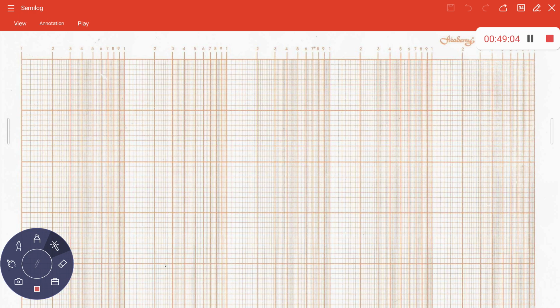They are the same. So along the x-axis there is a change, because I would like to observe the change from say tens of hertz to hundreds of megahertz. Along the y-axis, that is gain. So what is the maximum gain you have got? If I just consider the fraction, that is 1.989. What is the minimum value? 0.24. It is possible, no? 0.24 to 0.9, it's possible. That's the linear variation. So this logarithmic variation is there along the x-axis, but along the y-axis, it is linear.